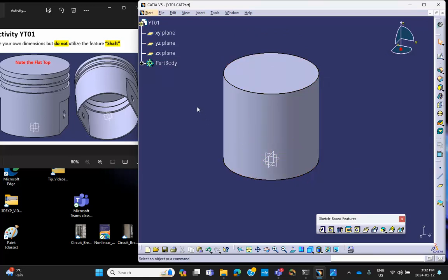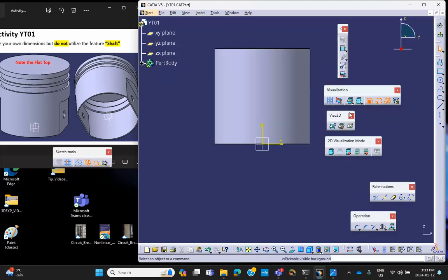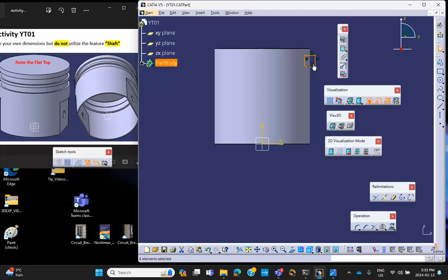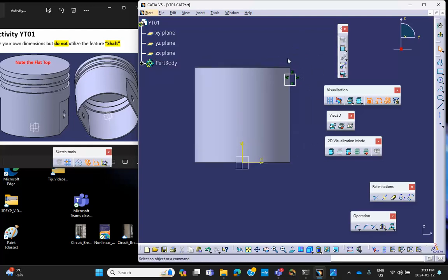Now, I want to make grooves around here, right? 2 grooves. Because of the way I did it in class, I drew the cross section like so and revolved it. Those grooves came up, but I don't have that anymore. So on that vertical plane, I will sketch a rectangle. This rectangle is going to make a groove out of that piece. In other words, you'll see how. I want 2 of these actually, and just to show you how you can do 2 of these identical ones.